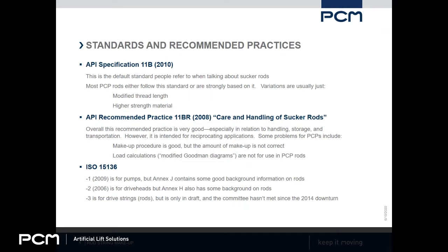-3 is the standard that I was on the committee for. It's only in draft mode right now, and it's the one that if it eventually gets published will really be important for our industry, because it's specifically for rods being used to drive PC pumps. So it'll have some really good things in there, and to me the most important part of that, if it finally gets published, is coming up with ratings for sucker rods. How do we rate a rod for torque?